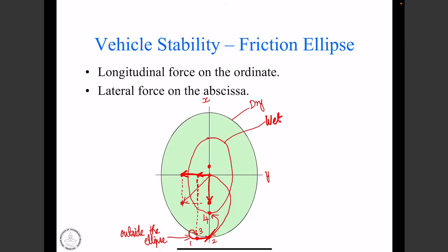This is once again achieved by reducing the brake pressure from the level commanded by the driver. There are multiple important points that we need to note. ABS by itself is not an autonomous brake controller. It intervenes only when there is a chance of excessive wheel slip and resulting wheel lock, and it prevents that by reducing the brake pressure.